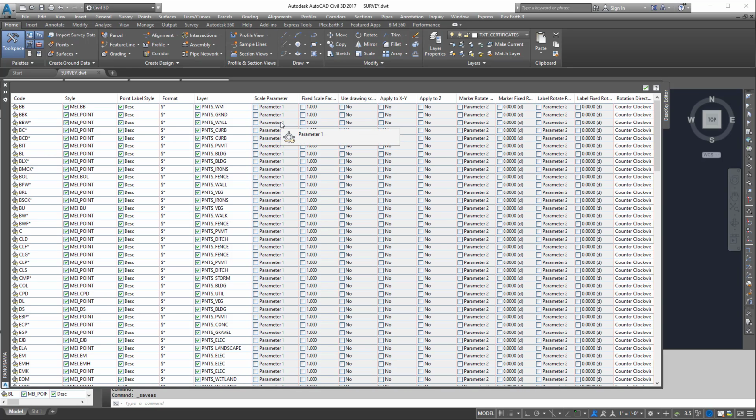There's a slight trick you can do with trees that includes you putting TRD, which would be my code for tree, and if you add a space, then the number, you can have it drop the TRD and just put 3 inches right next to it. So that's a little bit of a trick. I'll show you that a little bit later in the video probably, or if not, the next video, depending how long this gets. But so here's all my description keys.